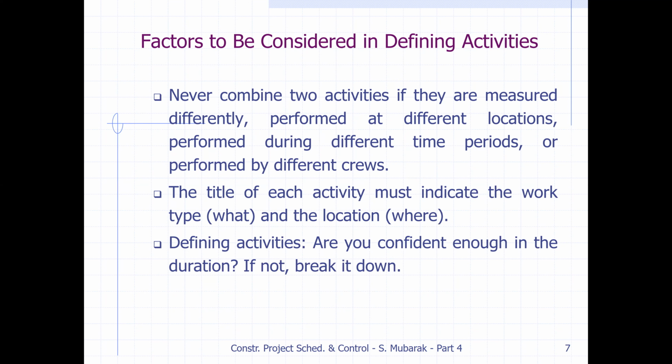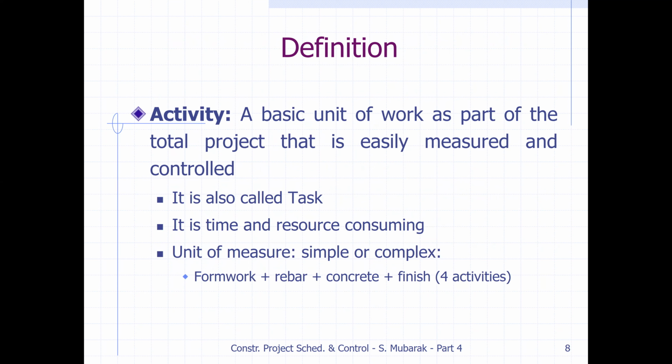Then, how to define activities. Are you confident enough in the duration? If not, break it down. This is a general principle: if we don't understand, we should break down our activities. Especially for the duration, we should also involve the management, like the site people. Not only should the planning engineer decide the time by himself. He should involve the construction manager, the project manager or the site engineers to decide the duration of those activities.